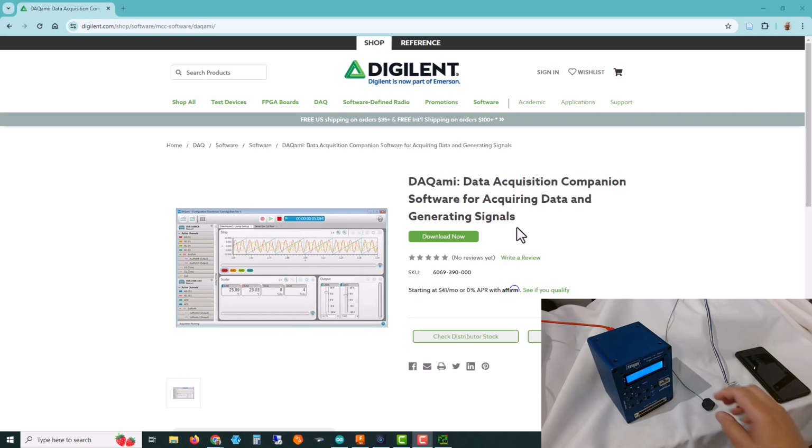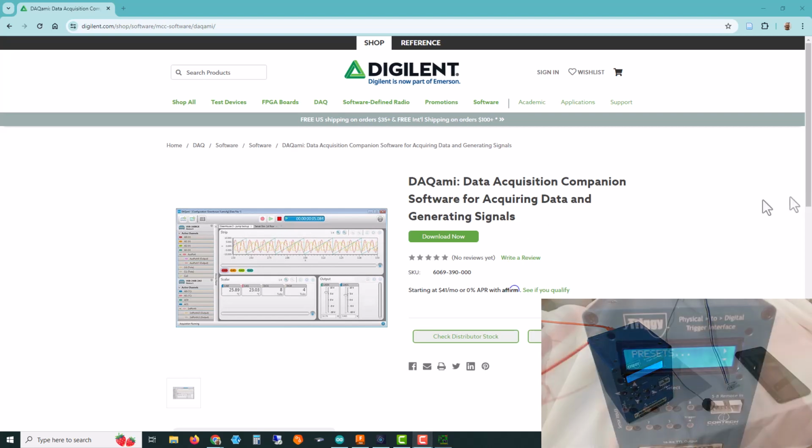So it's receiving its power from channel 8 and it's providing signals back on 5, 6, and 7. In order to accomplish that, we have to set these channels in different modes. The first 3 need to be set in audio, and the last one needs to be set in photocell or response mode, and it needs to be adjusted from that mode so that the threshold is at the maximum 100%.